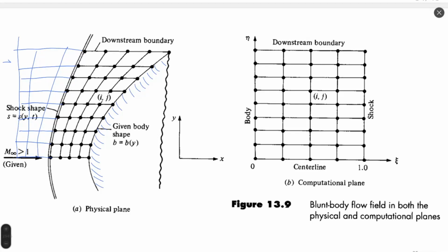And we define our boundary conditions, inlet, before the shock wave. This is the way we do calculation in our supersonic diffuser work too, right? We know approximately, but we don't know exactly how the oblique shock wave will be placed in space. So we simulate a bigger volume, and inside this volume our shock wave will be established.